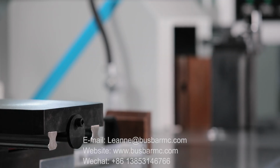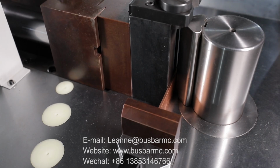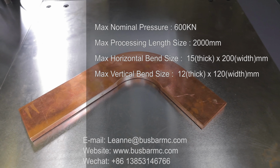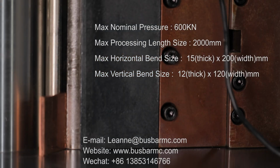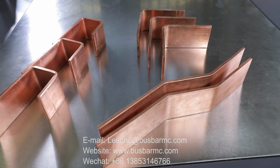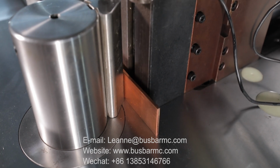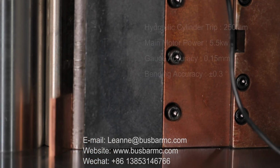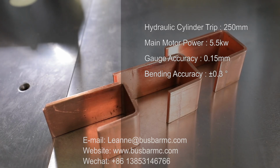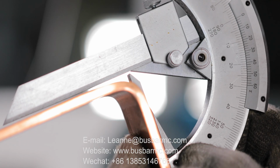The NC40Z series CNC bus bar bending machine has a maximum machining length of 2000 mm, a flat bending maximum machining size of 16 by 200 mm, a vertical bending maximum machining size of 120 mm, a material deviation accuracy of plus or minus 0.15 mm, and a bending accuracy of plus or minus 0.3 degrees. The minimum internal gear pitch is 40 mm for U-shaped.